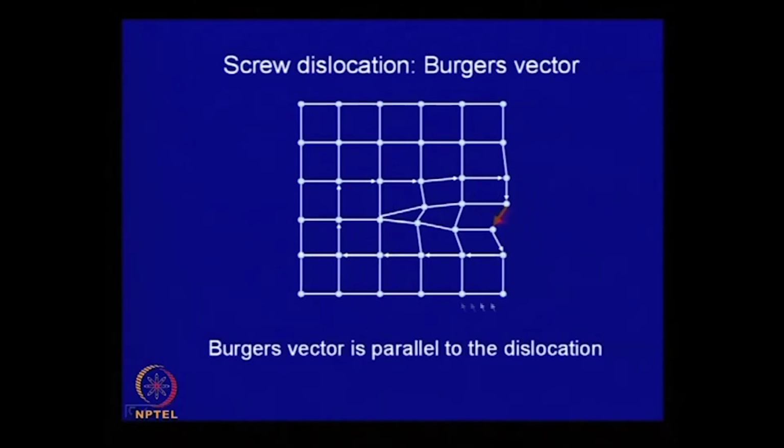So, basically if we consider this is the x axis, this is the y axis, and this is the z axis, this is along the positive direction of the z axis, and this type of dislocation is called a positive edge dislocation. In the same way, you can have a negative edge dislocation, where you invert it like this. Here this top part has gone behind the plane of this drawing, whereas if you imagine this top part comes out of the plane towards you, in that case this slip vector will point in the direction opposite to the z direction. So, that type of dislocation we will call a negative edge dislocation.